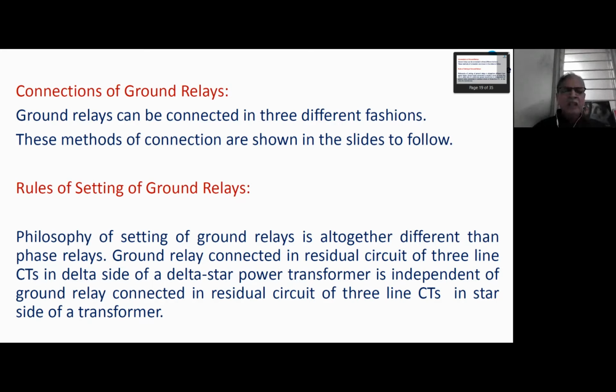Delta star connection filters out third harmonic. So third harmonic filtering is very necessary. Many of our loads nowadays, like thyristorized controlled induction motor drives in large industries, and UPS, that is the power supply that we are using for computers and many other things, are all non-linear loads generating large amounts of harmonics. If those harmonics are transferred to the generator, then generators are damaged, right? And even transformers are damaged by harmonics, because iron losses will be large.